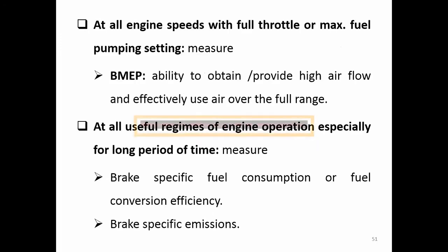Okay. We also run the engine at all engine speeds with throttle wide open or maximum fuel pumping setting. That means we deliver the maximum amount of fuel to that engine with the throttle fully open, and run at all available engine speeds. At this condition of running the engine, we will measure the BMEP. We measure this BMEP so that we can know the ability to obtain or provide the high airflow and effective use of the air over this full length of the engine speed.